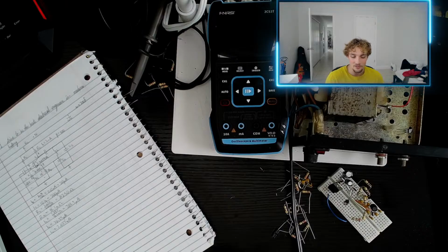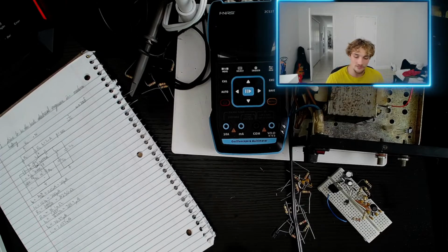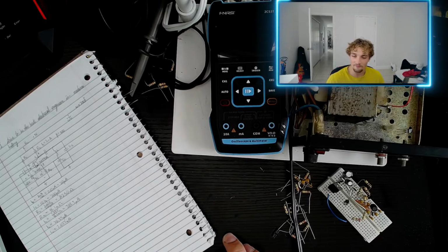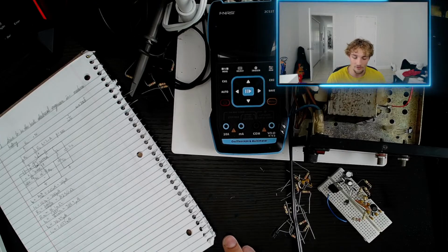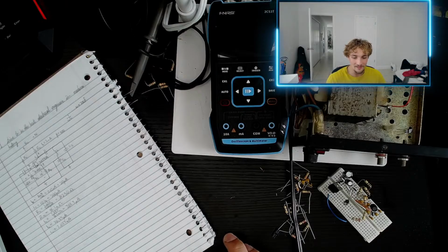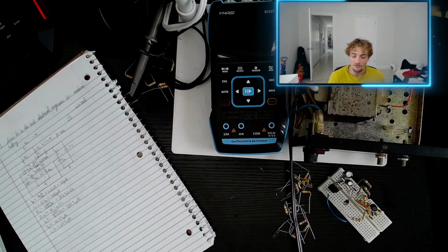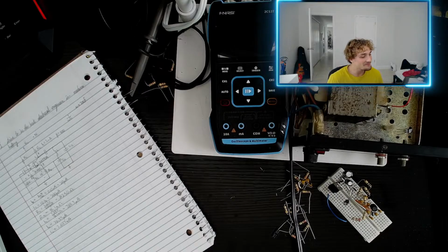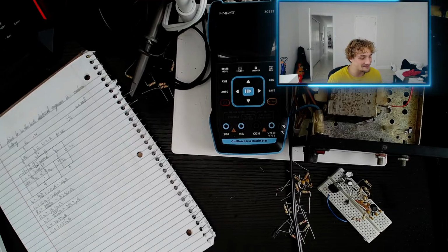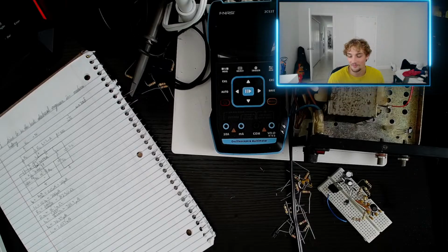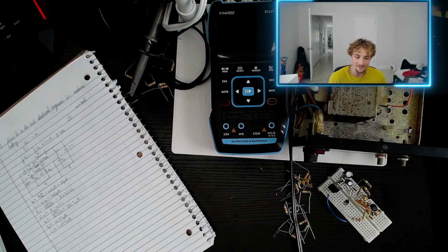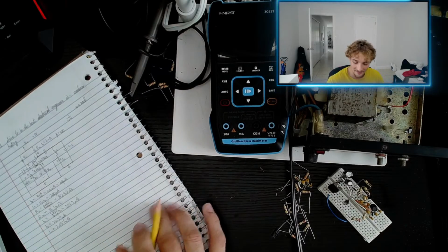And a square wave can be used for clock signals, used in memory elements such as flip-flops, which make up registers and components of computers. We can also use square waves for pulse width modulation, used in boost converters, and for very high precision control of motors, like servo motors. So it's real nice and dandy.